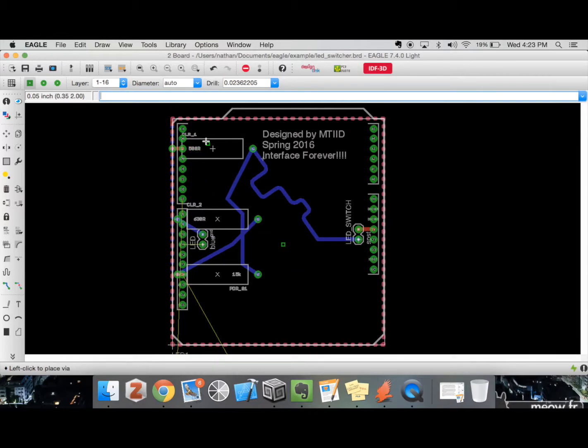But let's say, for instance, instead of using through hole resistors, we're using surface mount resistors, which mount on only one side of the board and don't have any connection to the second side of the board. We would have two different ground planes. One way to combat that is by placing some vias on the board in order to connect our two different ground planes. So we place the via, and then we get some options on the via. We get options as far as the general shape and also the size. So we have round, and square, and large, and small.